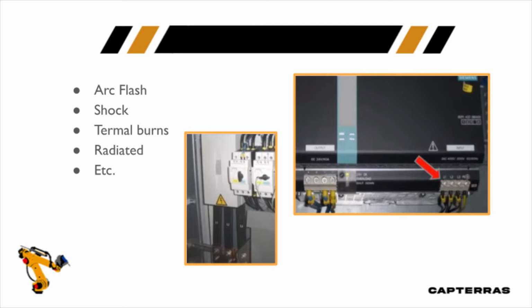And when you get into the power supply, if you look very closely, and again, it's much brighter here because I've changed the picture a little bit, you see at the input on the lower right of that picture, where the red arrow is, it says 400 to 500 volts input in a non-finger-safe terminal block there. They weren't even aware that 480 volts was in the cabinet, yet they were working barehanded. So again, this is a violation of the OSHA requirements and NFPA 70E. As we see folks working, they should fully understand what they're working with, assess the risk, and make good educated decisions on how to protect themselves.